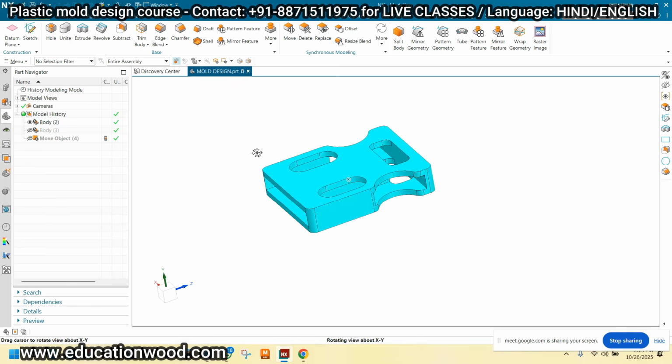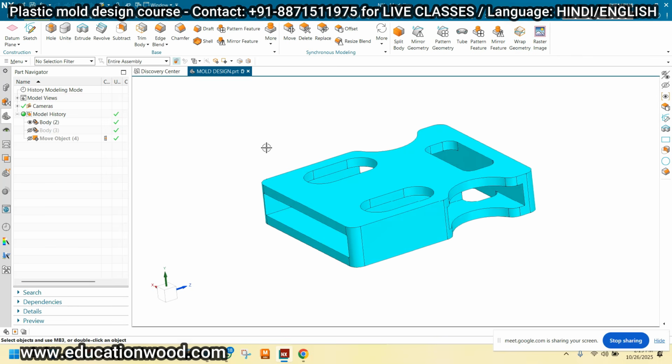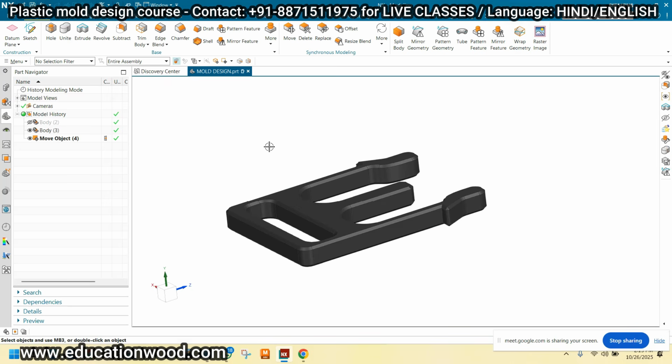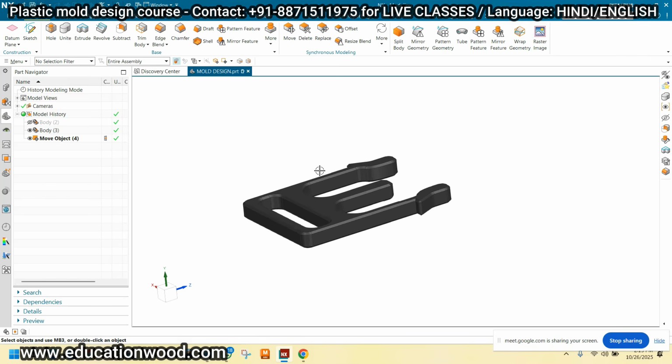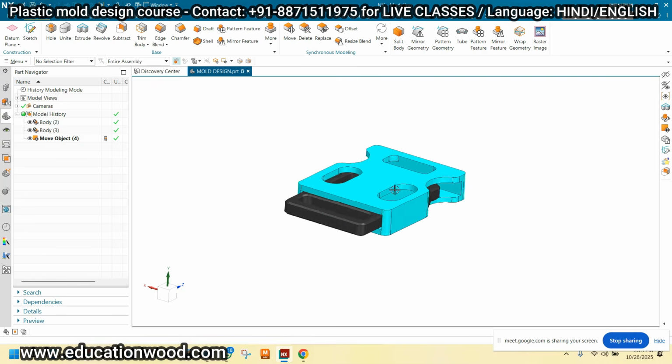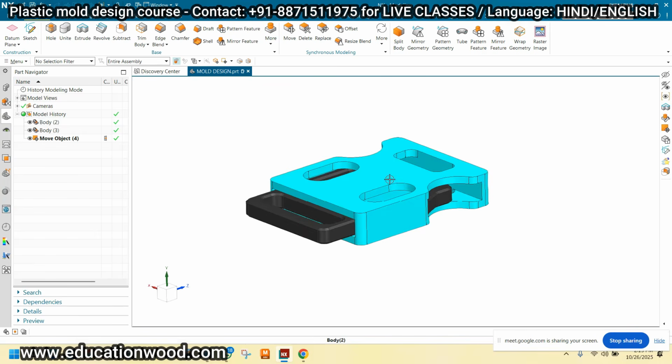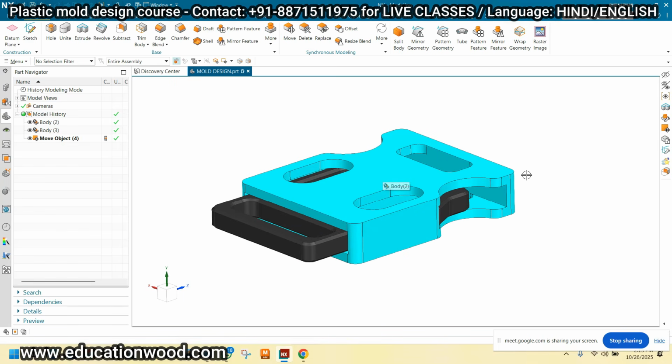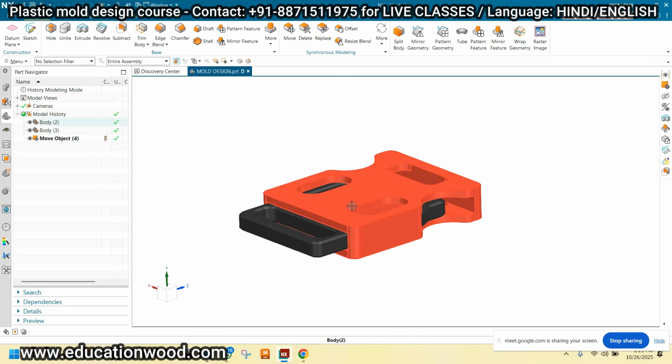Now, for example, where is the hidden component? Just press Control Shift B, B for ball. Okay, Control Shift B again. So it is known as invert hide and show. Now you want both components on one screen. So basically, Control Shift U, U for umbrella. Control Shift U. Okay, so both components or all the components will be on one screen.